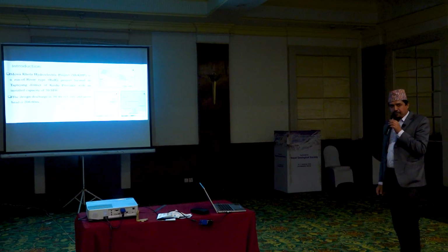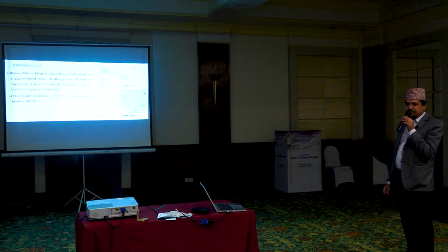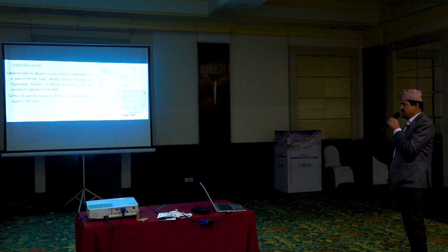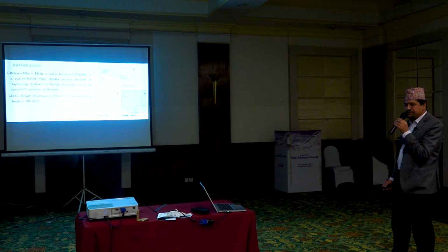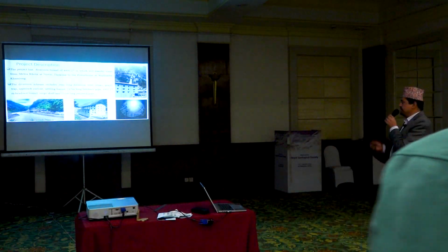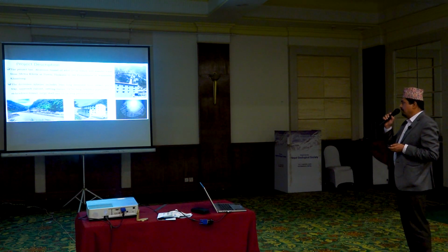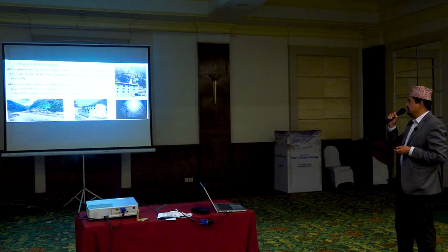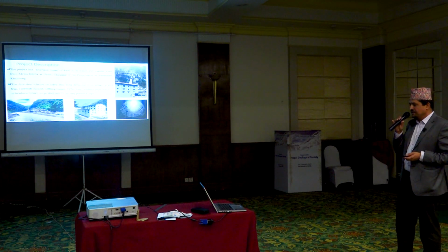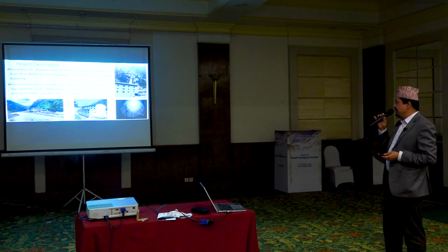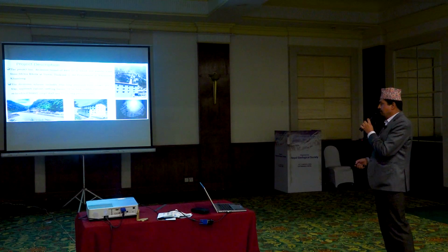Nearapala Hydroelectric project is a run-of-river project. It is located in Kathmandu district in Bagmati province and it has a capacity of 50 megawatts. The design discharge of the project is 30.48 meter cube per second and the gross head is 206.60 meter. The project has a headrace tunnel which is 4.8 kilometer, which will transport water from Tukima to the powerhouse at Khundin. The diversion scheme includes a diversion weir, intake, gravel trap, approach culvert, settling basin, headrace pipe, surge shaft and 531 meter penstock pipe.